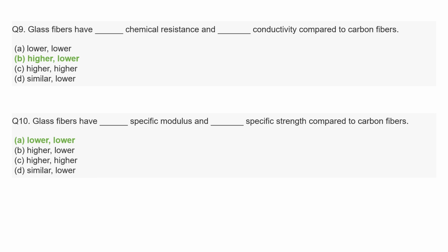Our first choice has to be the reinforcement, because reinforcement is the load bearing constituent. So we will choose our reinforcement. Then comes the matrix that combines with that reinforcement. There are always different grades of reinforcement and matrix, and you can't mix one type of polymer with any type of reinforcement. You have to study the TDS and see which kind of reinforcement is compatible with which specific type of matrix, because if they are not compatible, then the strength of the total composite will not be that good. So we have to study that when we are choosing which type of reinforcement and matrix we have to use.